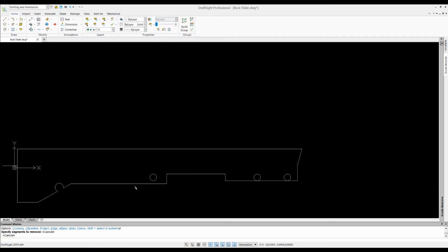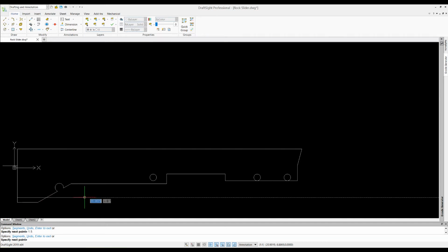Now let's put in our mounting bolt holes. We have to remember this area, there's no frame. The frame is following this. So that's where we'll put all our bolt holes. It will be along here and here and down this way. An easy way of doing it, I'm just going to snap up. Let's start our holes 1.5 inches in. That should be good. We'll just snap a nice straight line there.